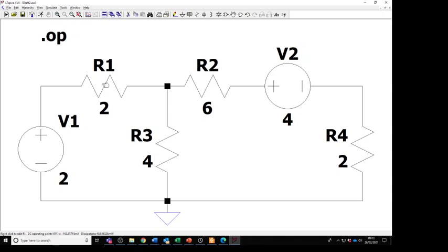So this one here, we can see the current is minus 142.8 milliamps. Again, it doesn't tell us which way is the positive direction, and that's the slightly annoying thing about it. What we have to do is know that current flows from high voltages to low voltages, so we have to look at the voltages at either end. That's 2 volts, and that's 1.7 volts, to know the direction of positive current. So it's going to flow, in this case, from left to right.